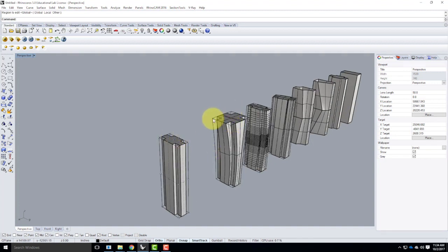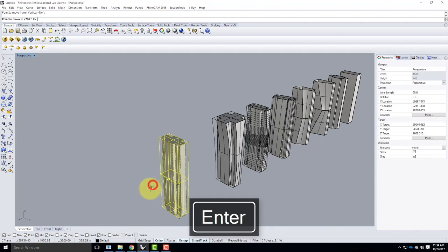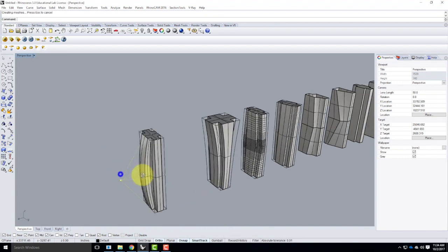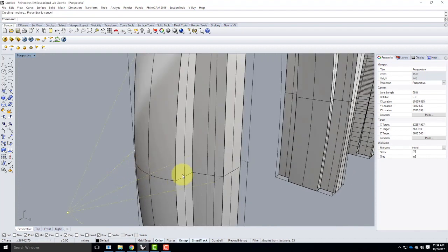So on those last set with x and y set to just 2, I had just a single control point on each side. If I go to 3, I have control points in the center. And so you can see I can add to the complexity. So for example, I could take this point and move it out and cause the side of the building to bulge. This obviously is curving in 2 directions. It's curving this way and that way, which means I couldn't roll it flat. It's starting to be a spherical curving object.